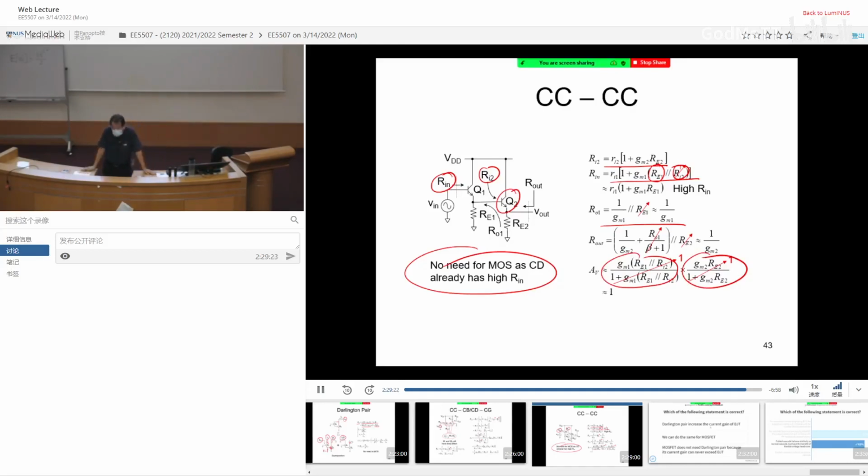In power amplifier, there is this concept called driving amplifier. Have you heard of it? Driving amplifier. So power amplifier, I want to drive 50 ohm. Usually this 50 ohm end up having a very large transistor. So if you have an audio amplifier directly driving this guy, that is like, how should I say? I have a lorry and I'm driving a Mini Cooper, trying to push this lorry. It's not going to work, am I right?